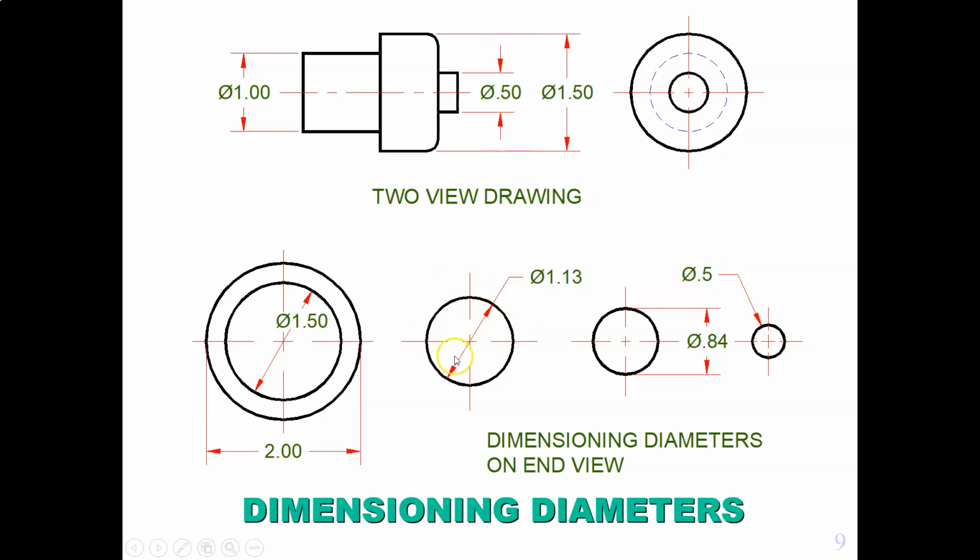This is one of the other options that we're seeing a lot now using AutoCAD, is we have the arrows here, and even on great big ones, a lot of times we'll have people now putting them inside the hole. But this is, again, this 1/2 inch, the most common way. This diameter here is probably the least common way of doing it. So these are all for holes.